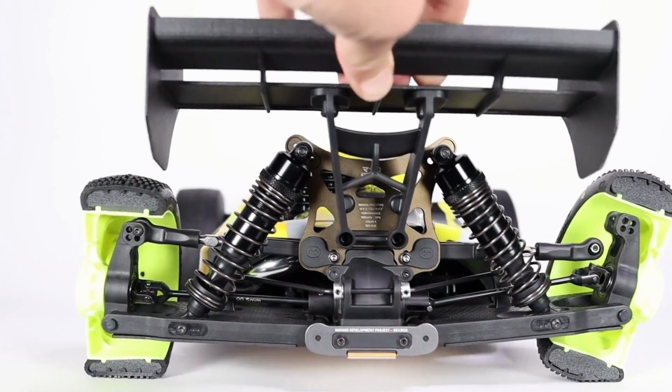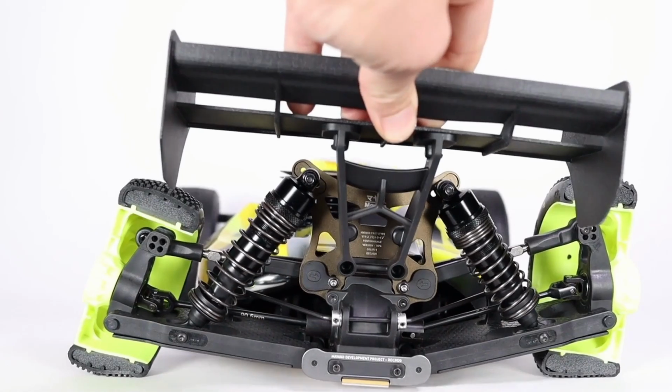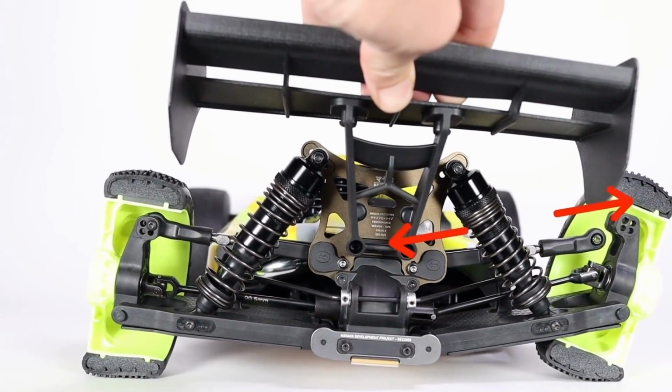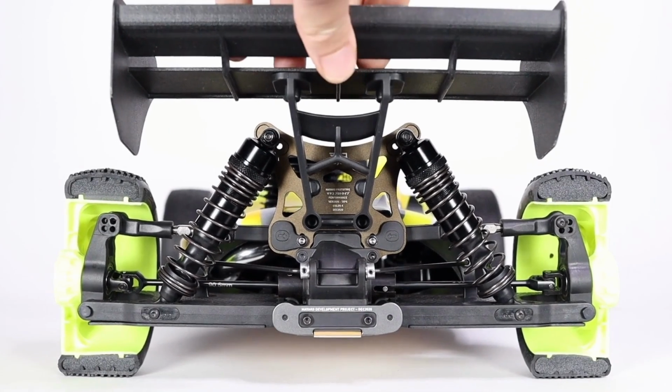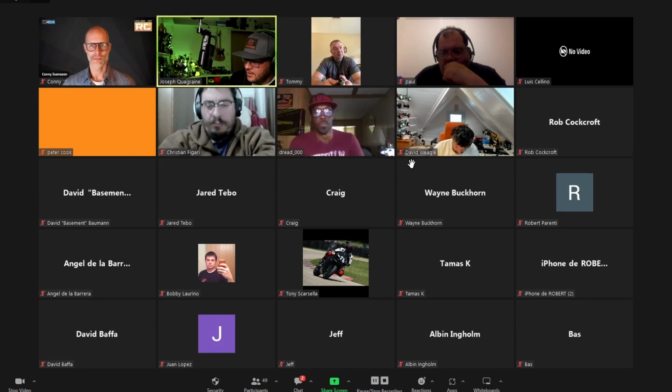And there you see, the outside tire flips into positive camber. Now I remove this screw on the inside. And the inside tire flips into more negative camber. So we can see that the outside link is under tension. The hub is pulling on the link and it's pulling on the chassis. And on the inside, the upper link is being compressed. So the hub is compressing the link, pushing on the chassis. So as you can see, there are forces that are traveling in the upper and lower arms of the car. And how much of the force goes into the link and arms and how much goes into the shock spring is determined by the roll center height.